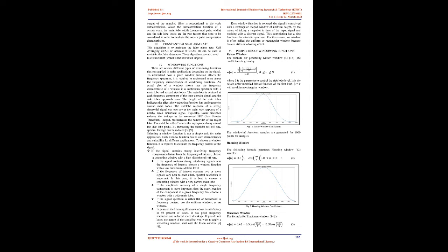Range resolution is the ability to detect two targets in space that are close to each other. If the transmitted pulse is wide enough to simultaneously dwell on both targets, the returned signal will appear to the radar as a single target. The key to solving this problem is the realization that the range resolution of a radar does not necessarily depend on the duration of the transmitted pulse. In fact, it depends on the bandwidth of the pulse.